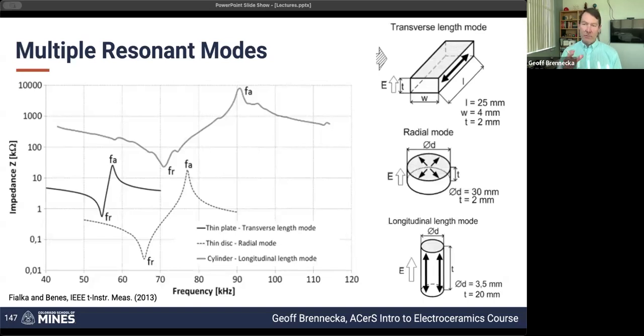Hopefully that makes sense. But remember that the whole reason that these resonant measurements work is because of that coupling between electrical and mechanical. And by doing these resonant measurements, we can measure essentially the different pieces of the Heckmann diagram that we're on. So at low frequencies, we're under a zero stress, so free condition. At high enough frequencies, we're effectively clamped, so it's not able to vibrate.